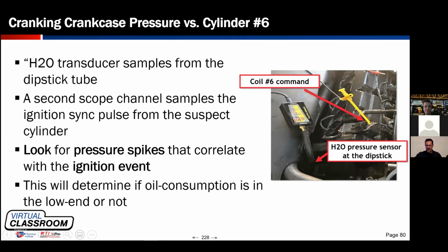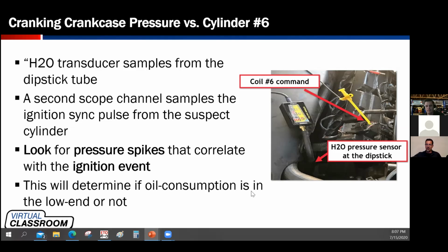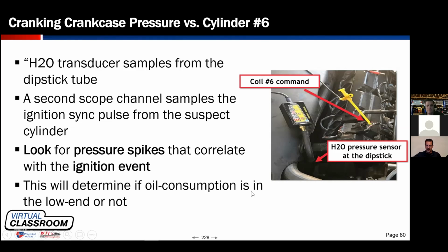I don't feel it necessary. For one, how many PCV systems are built directly into the intake manifold by way of a fixed orifice where you can't really alter them? Or look at some of your Euros, where everything's all integrated into the valve cover. I don't even think you're capable of separating it quite easily. So I don't bother, because we're looking for change. The point is, one of the 8 cylinders is not going to be like the others. I want to see, is it going into the crankcase or is it not going to the crankcase? So I should still see a difference.